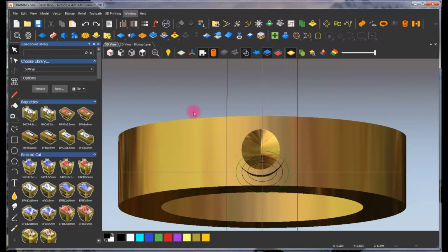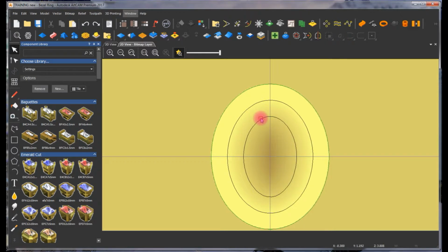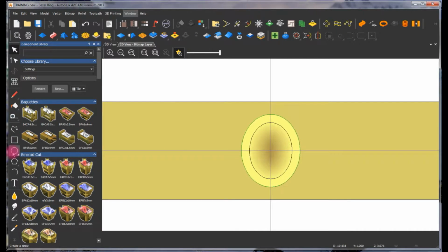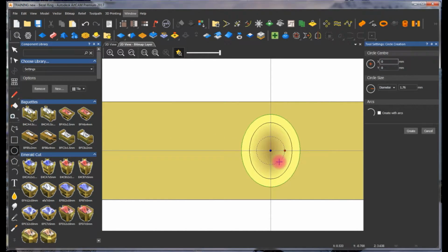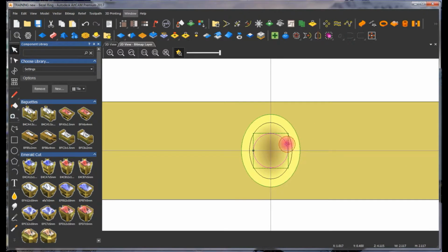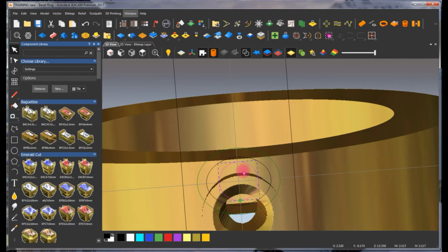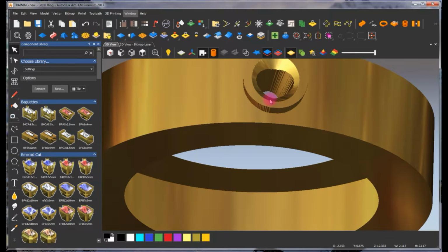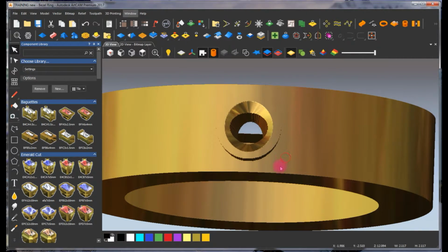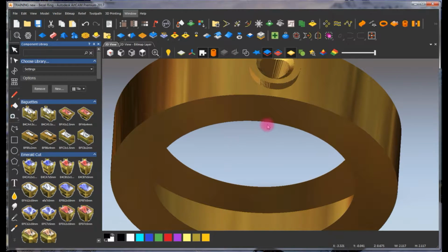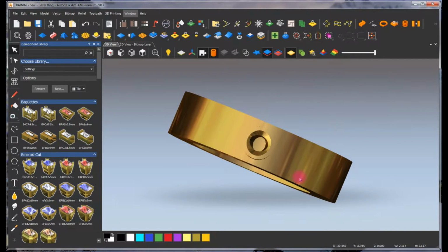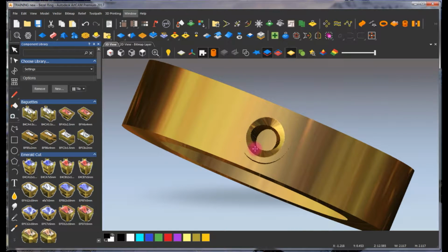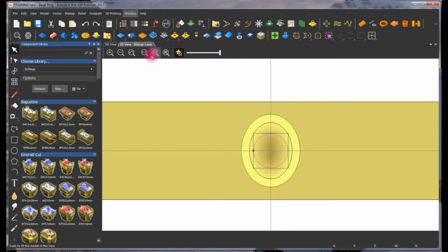So let's say Control Z, bring it back. Let's see what happens if we draw a circle on top. Okay, let's see if that will take care of our problem. So let's do this here. Punch this 0. Ate all that away, so that's no good either. When you mill this, I know when you set it you won't see it, but if you look at it, people are going to think it's oval instead of round. All right, so Control Z, that gets rid of that.